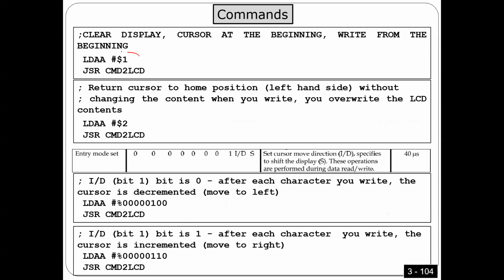We have one command here, where the code is number one. This one clears the display. We have another one here, which is number 2. This command returns the cursor to home position. I also explained last time that some of these commands you may not need much, or you may need them in some special cases, something like if you want to do some kind of rotating text, but it's not going to be in the basic use of the LCD.